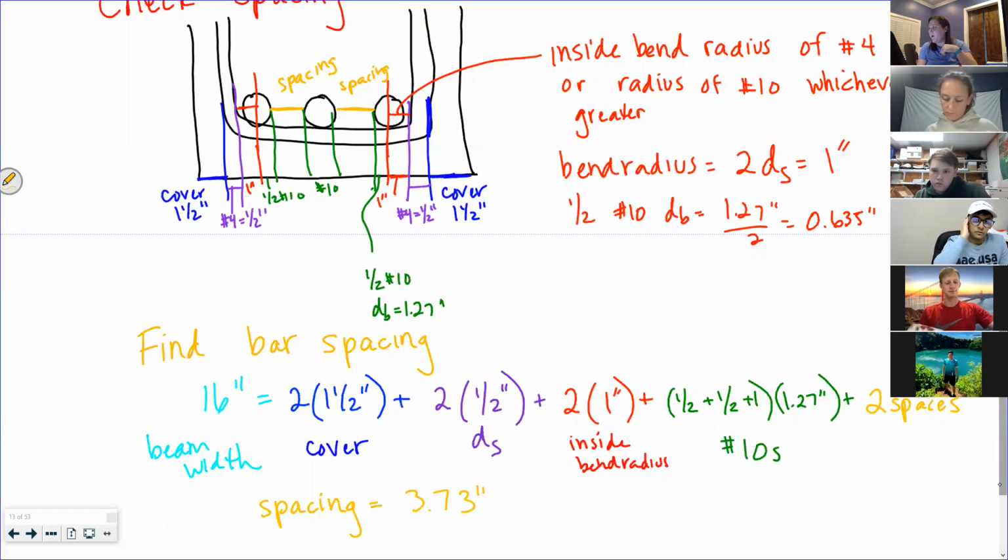We're talking about 0.4 inches on either side, half an inch. You used the 0.635 for the bend radius instead of 1. Did I miss something? Why did you use 1? Because we're going to use the maximum, since we want the longitudinal bars resting on the bottom, which looks a little bit better on the other side. So you take the maximum of that chart.